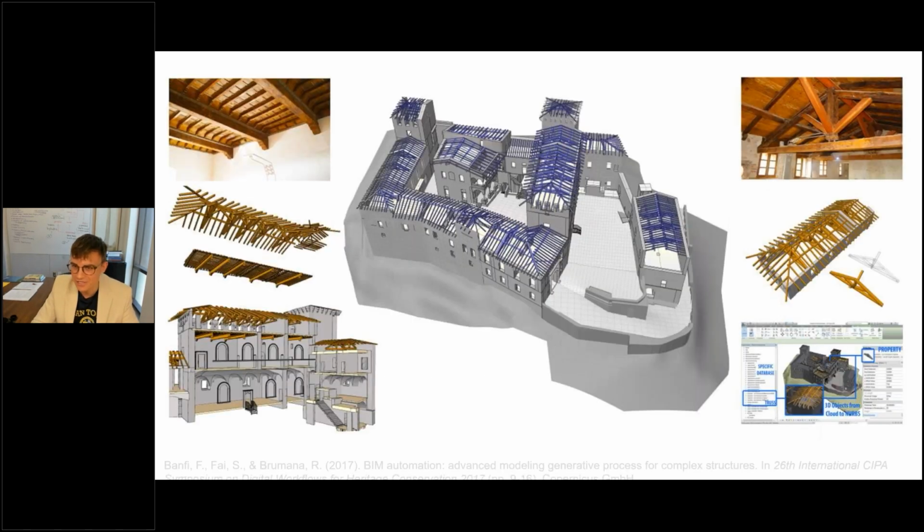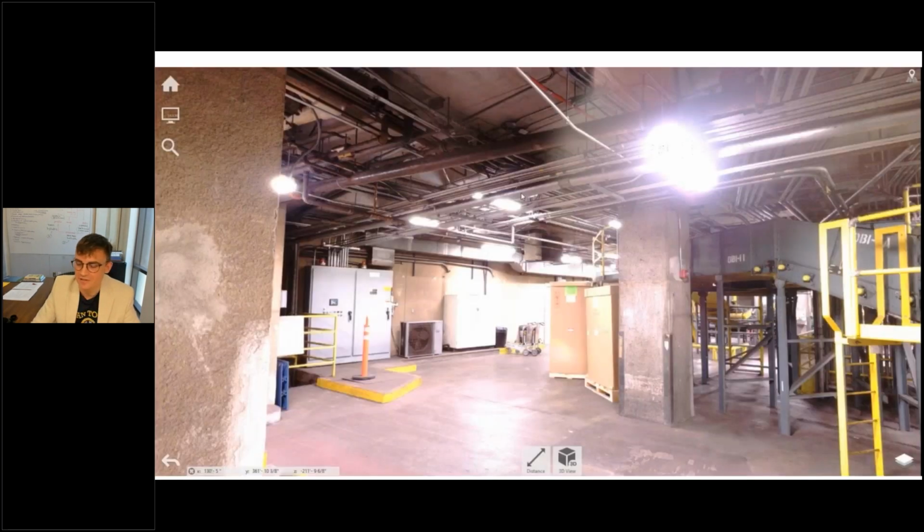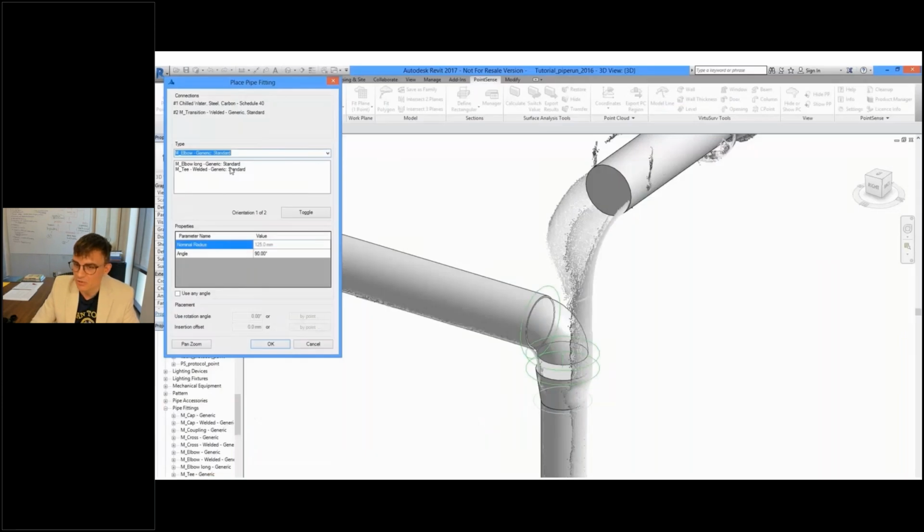The amount of automation you can employ depends on two things: the type of building and the disciplines that you're modeling. If you're modeling a castle, your amount of automation will probably be zero. You're going to want to carefully interpret the point cloud data and make sure that someone specialized in this kind of architecture is there to help. If, on the other hand, you're modeling an industrial processing plant or an aircraft hangar, then 80% of the piping and structural steel can be automatically recognized. These simple extruded components can be modeled using semi-automated and fully automated tools.